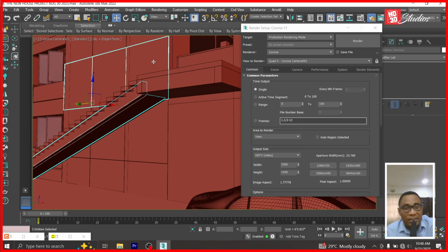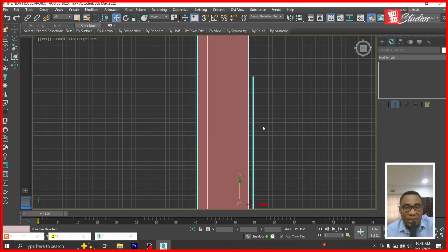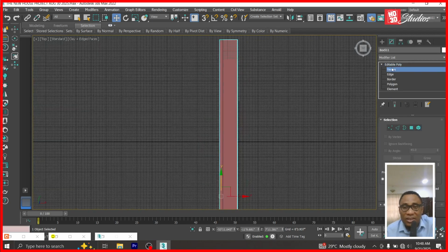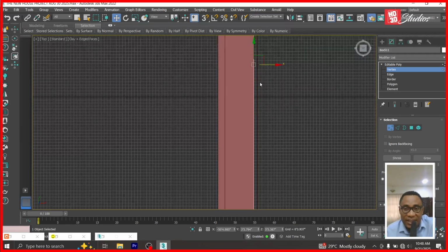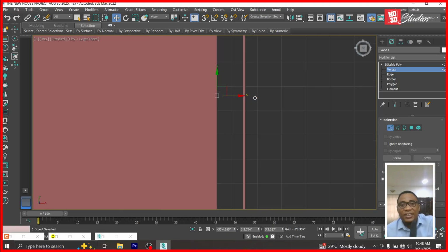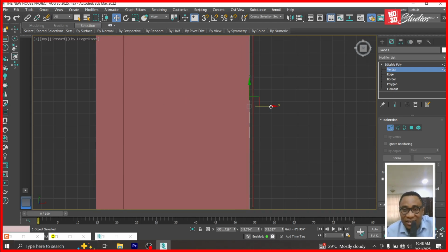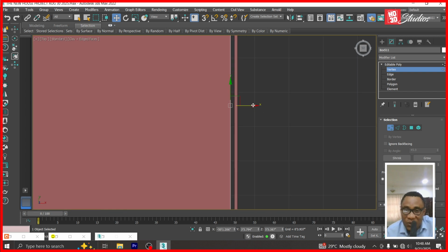Now I'm going to select this guy, and let's say this, just for, unselected top view. Now I'm going to select OK. So this is the stair ceiling. Sorry, the bottom of the stairs itself, I created the white ceiling. It did not get to where it should, so I'm letting it go through the wall. This is just an aluminum panel that I'm using for reference. I don't need it for anything else other than for reference. I just need to stretch this ceiling to make sure it touches it. That's why I have this there.